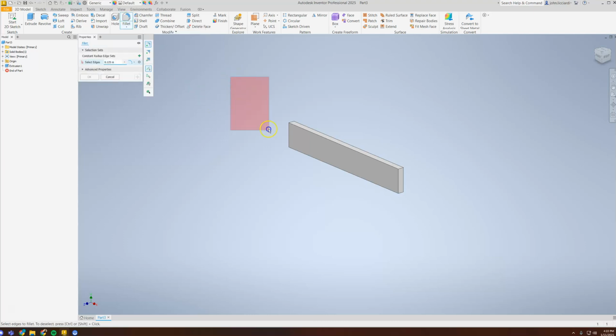All right, so how to do that is we're going to click on Fillet. We are going to click and drag, hold down, let go, and you're going to highlight all of these edges, okay, all of these corners. When you do that, change it to 0.0625. Now notice it's 0.0625. Now watch what happens when I just put in 0.625 and I hit enter. It's going to say, hey, wait a minute. The dimension you're giving me is not going to fit on this piece, okay? So what we want to do is